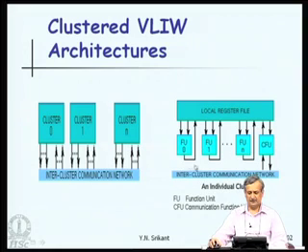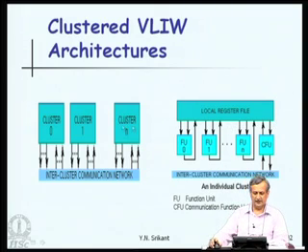The problem is that when we look at just the function units, they can possibly have a local register file and communicate within that, but when we look at clusters, intercluster communication is not cheap. This is the reason for concern. So, we need to allocate clusters and function units very carefully. Within the cluster, we need to make sure that energy is saved when we assign the function units.